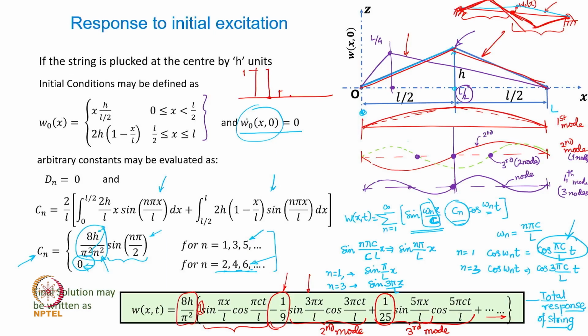So this is how, even in a 2 degree of freedom system, you have seen that if the two masses are initially moved together in one direction in the same amplitude and then released, it will continue to vibrate in the first mode only. If you stretch it in the opposite direction so that the mode shape is 1, minus 1, and then you release it, then the whole motion is going to be only in the second mode, the first mode will not contribute.